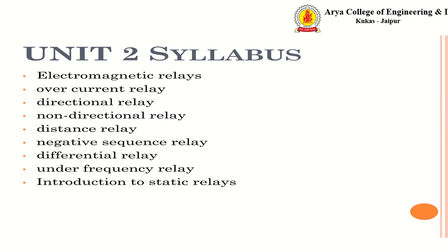if we want to give more priority to the generator, then we can use a directional relay, so that in any case, if any reverse fault current is entering the generator, then by detecting the direction of the approaching fault current, the directional relay will act and directly work for isolation and for the safety of the generator. That is why for such conditions where the directional property is judged, we use directional overcurrent relays. Similarly, non-directional relays can be used, having both directional properties.